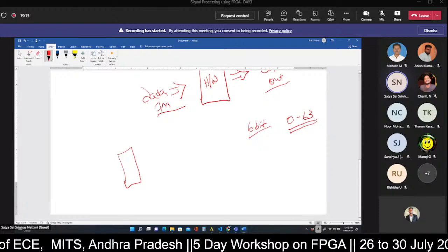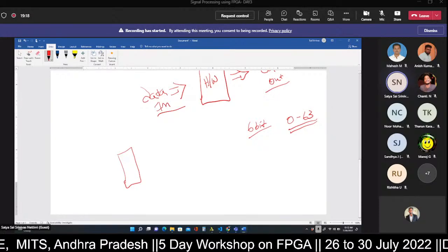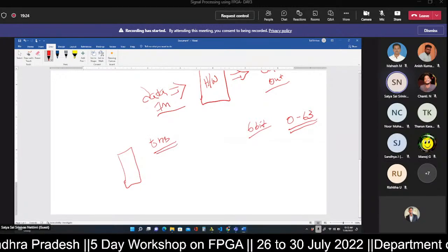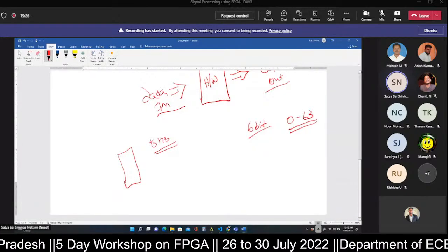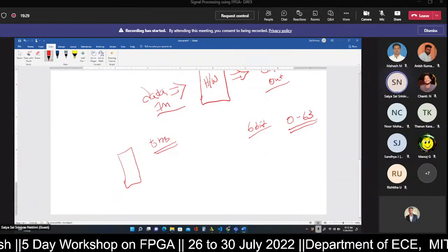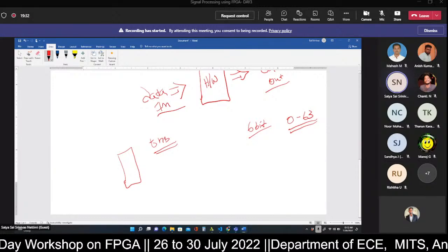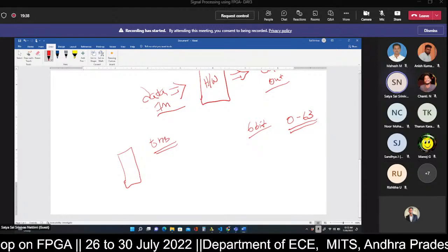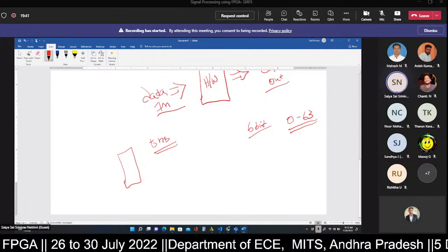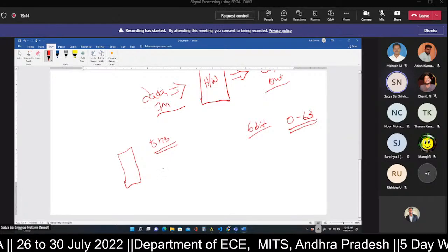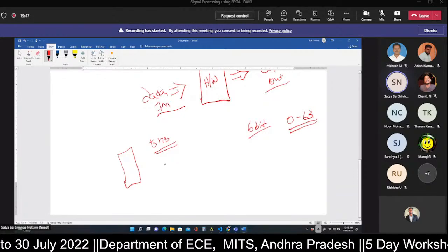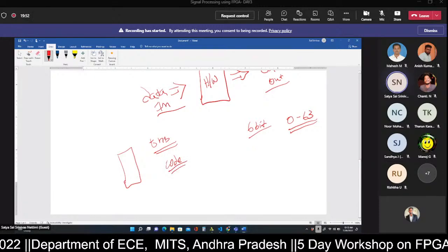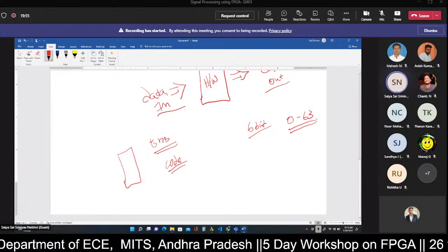That simulation we will run for some predefined time, say for t nanoseconds. And accordingly, the outputs are represented in the timing waveform. If you want, you can just scroll and check the data randomly. But since we are dealing with a huge amount of data, it is very difficult to check each and every sample, right? So for that purpose, within the test bench, we will write a few statements or code that is associated to handle the data. So how to handle the data?